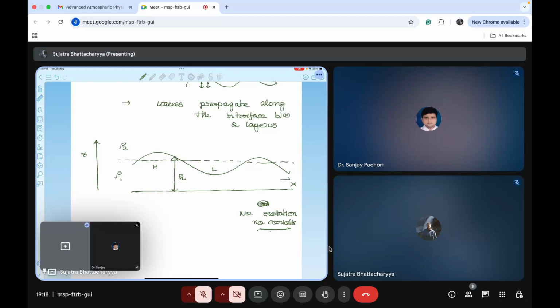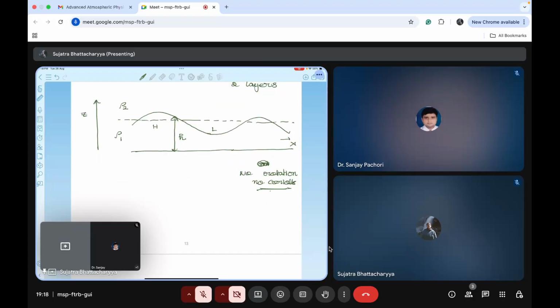Okay, so del p del x in the z direction, if you do this mathematically, can I write del x of del p del z? Yes. And what is del p del z? Using the hydrostatic approximation, you can write it as rho times g, which is constant, which is becoming zero.